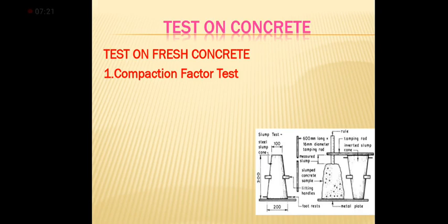If the water cement ratio is too large, means the water content is too more, that time the concrete will be a little fluid type, so it will be very much uncomfortable to work with it. And if we apply less amount of water, the concrete will be very solid, dry, so that concrete also not good. Thus, for workability, water cement ratio is very important factor, because the water amount should be adequate enough for going to the construction. For finding workability, we are having few tests.